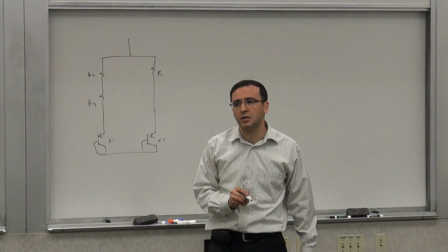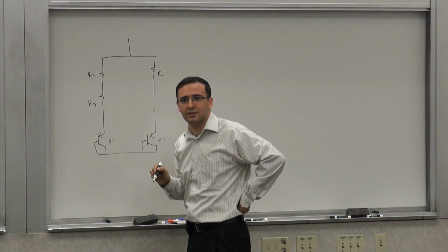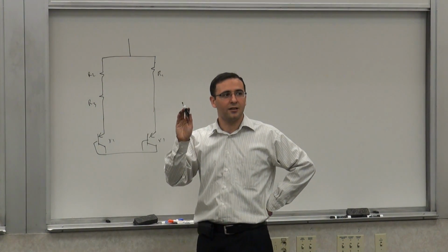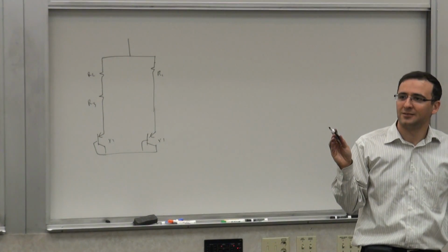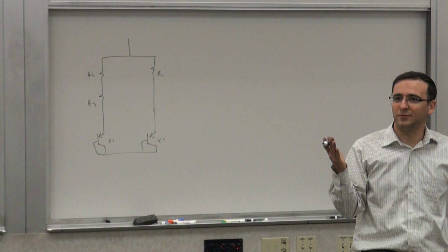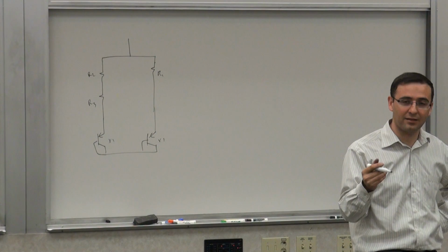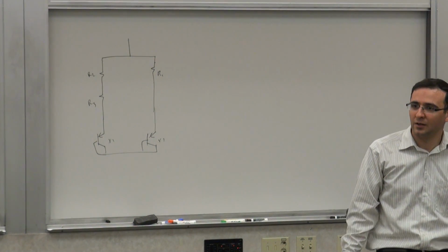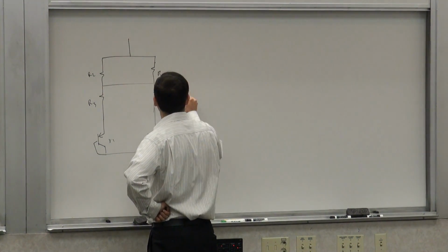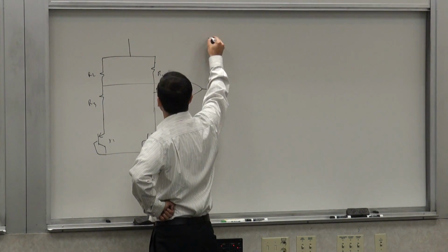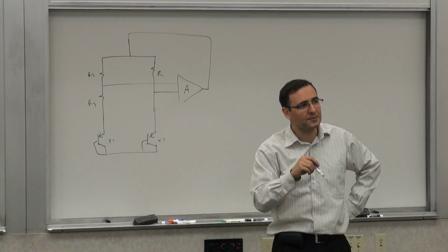In this case, if I wanted to force these two voltages to be equal, how can you do that? We learned the asymptotic equality principle. See, that's where that is useful in design. You want two things to be equal. You want to force them to be equal without driving current directly into them. You apply them to an amplifier with a gain of A, and you drive this voltage. Now you just have to pick the right polarity for the feedback to be negative feedback.